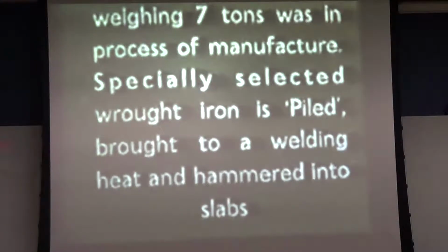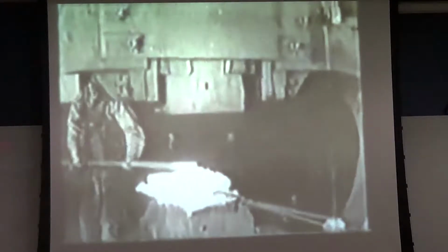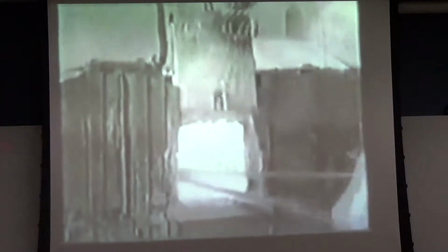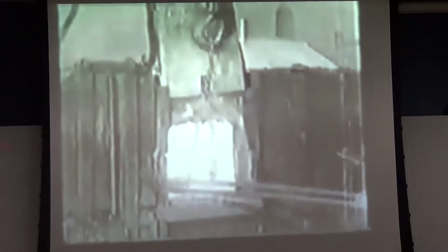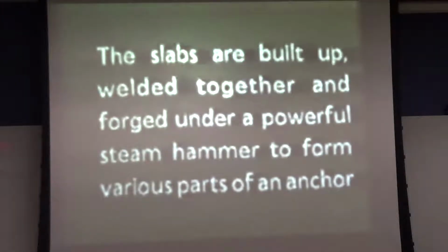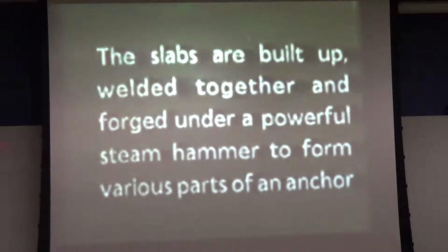The way they would do that is they would take cast iron, which has a low melting temperature, but very high carbon content, and they would remove the carbon by blowing an oxidizing flame over a liquid bath of cast iron. As the carbon content was lowered, the melting temperature would go up, and the furnace temperature was held to a spot just below the melting temperature of pure iron. So what would happen is you'd end up with solid particles. But the furnace was lined with sand, and the sand would tend to melt, and so you had iron particles in a liquid silica, or actually iron silicate fluid.